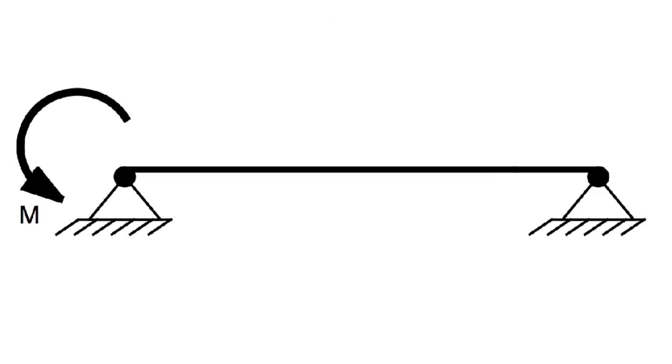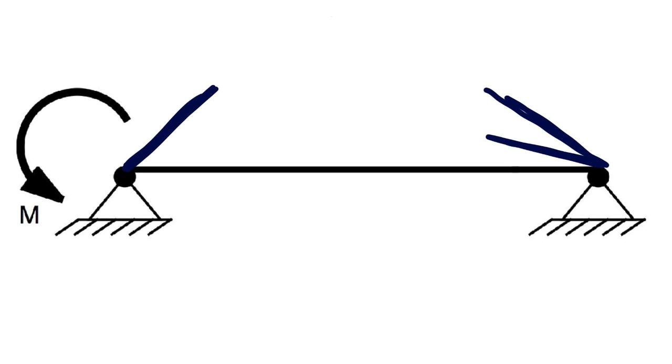Now, we consider how to sketch this case by hand. We start by drawing stubs or small line extensions at each side. We choose an arbitrary but exaggeratedly large slope for the stub on the left end. We do this so that the shape is clear. On the right side, the angle appears to be smaller. Theoretically, for this case, it is half of the other end. So, on the right side, we draw a stub at a slope about half the other end.